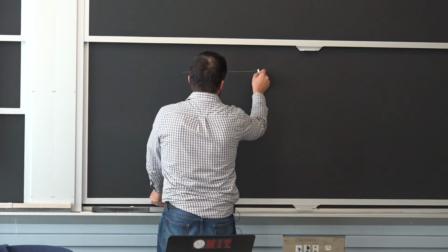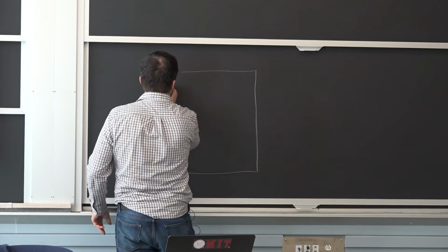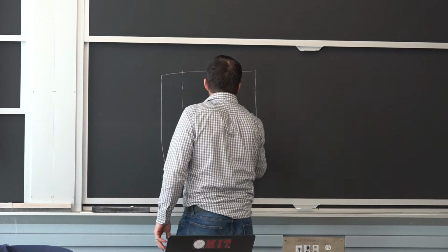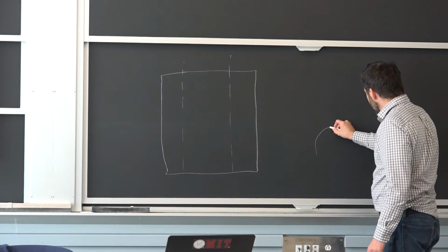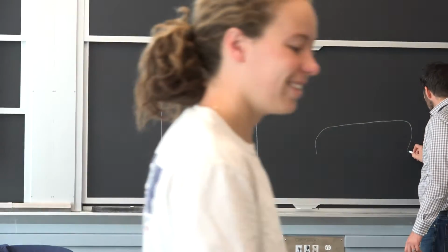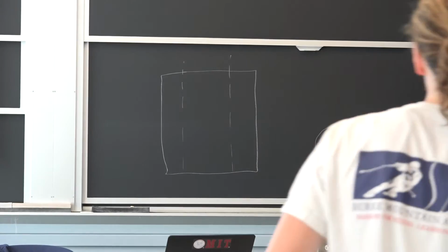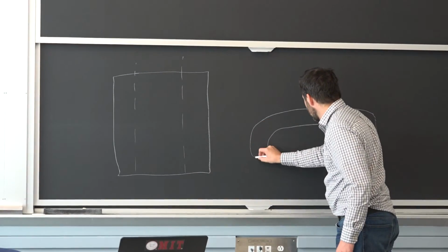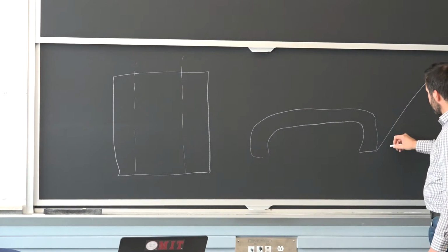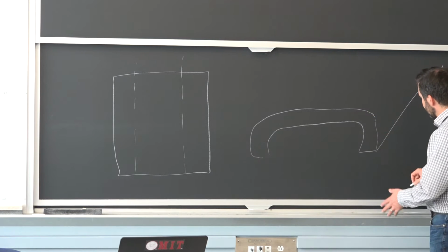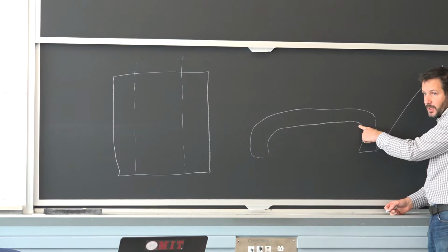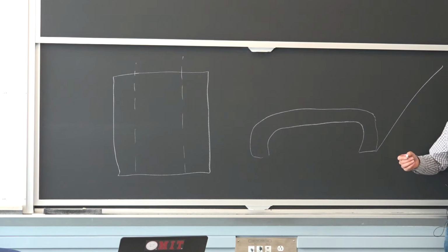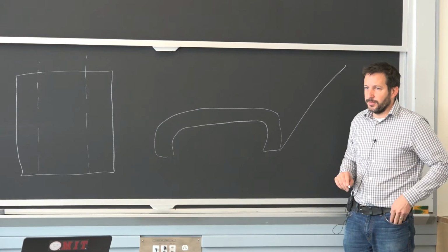Because you really take a plate and you say, I'm going to bend it here, and I'm going to bend it here, so you end up with this shape. So what happens is, as you bend, this portion is in compression, but as soon as you let go the closing force to form the shape, it becomes in tension.